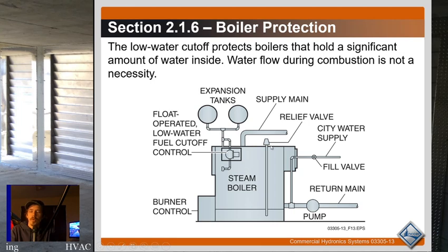And with the steam boiler, you don't want to have not enough water in the boiler. You can cause damage to the boiler or the piping system. So you always need to have a low water cutoff, or on a system that is filled all with water, you need to have a flow switch. One of the two. Low water cutoffs are often float operated, but they can be